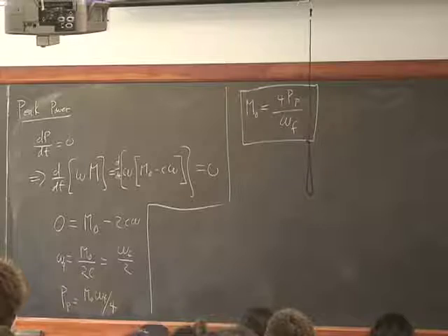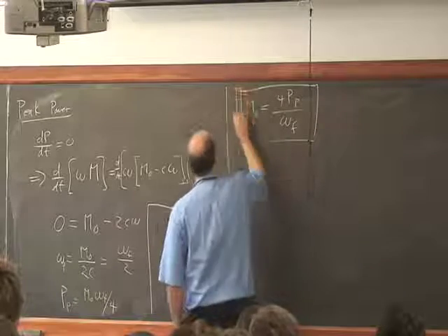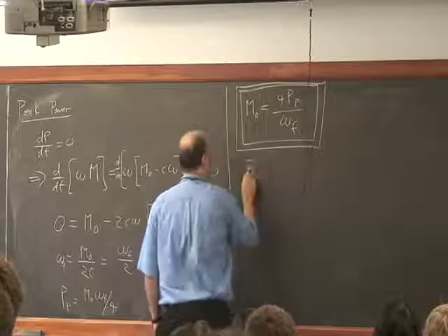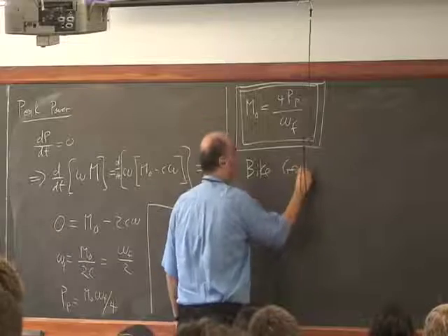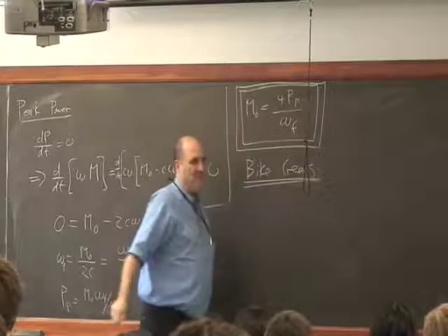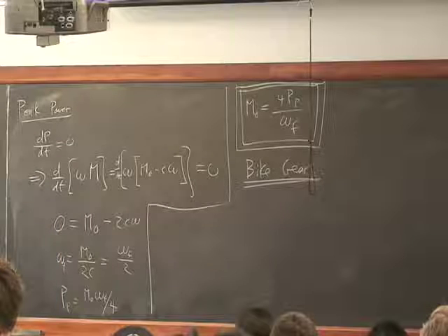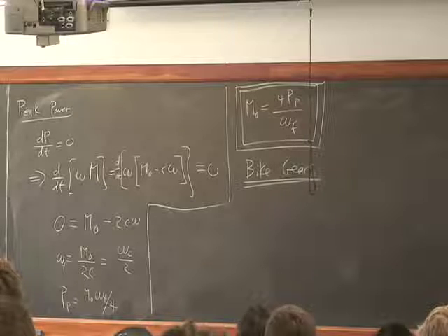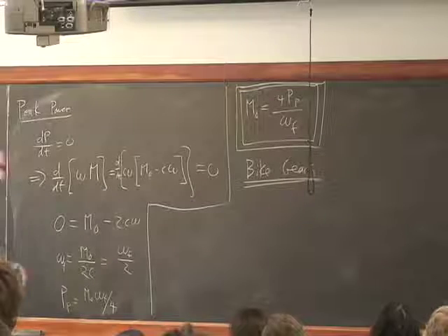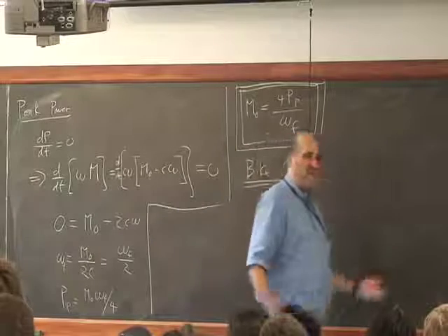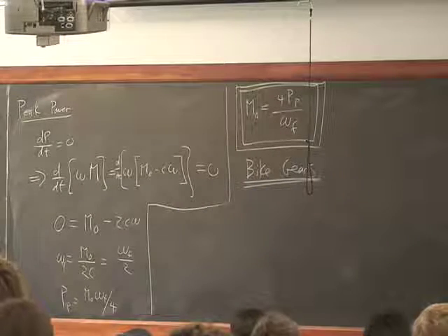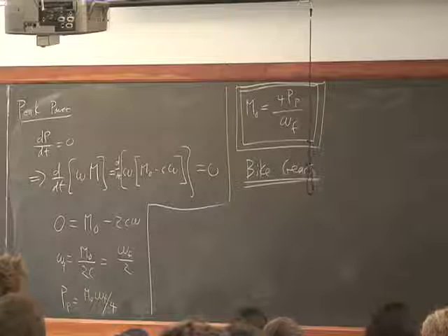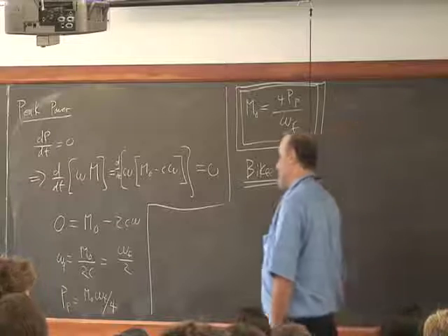Now the next part of the problem is dealing with the gear ratio on the bike. So how do you deal with bike gears? We have a few basic principles we can work with. One is that you think of the gear train as something which conserves energy. It has low friction, so the power in equals the power out. Another thing is that the parts have to work together, so the speeds and angular velocities are linked to each other by chains and gear teeth and radii and things like that. And a third thing is the various parts have to abide by force and moment balance.